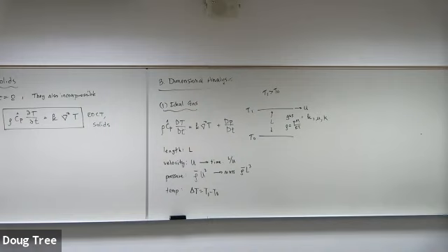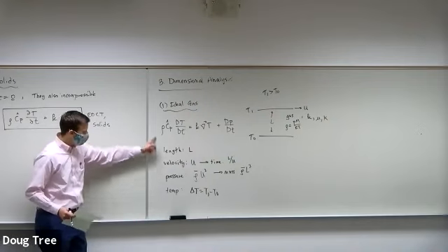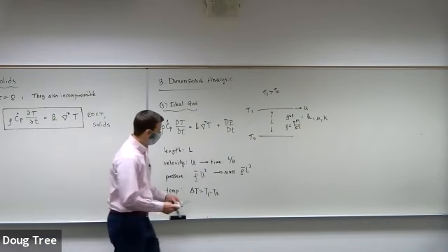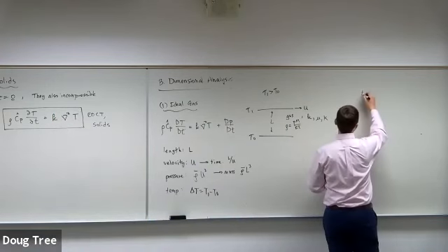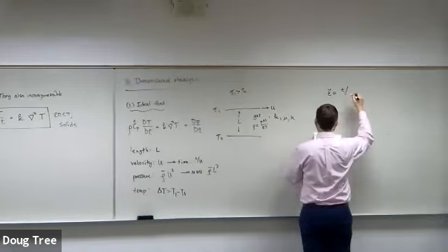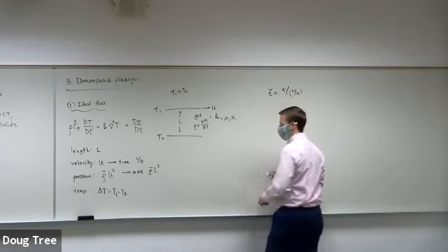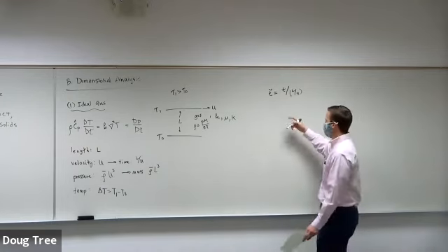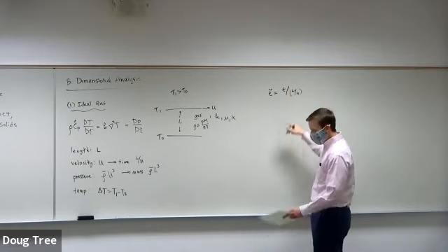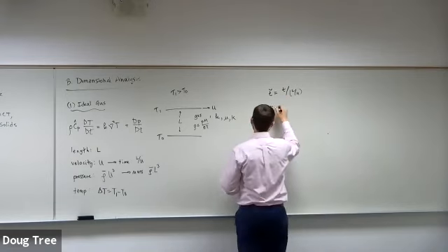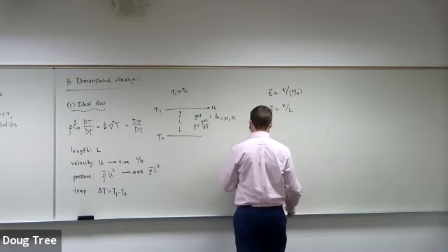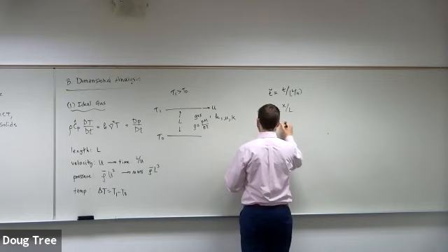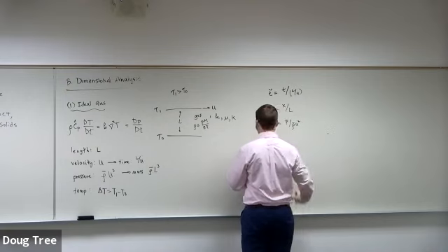Now we get to Andrew's step. Now we need to define all of our variables in the problem in terms of these dimensions, right? So for instance, I'm going to make a time, which is time divided by L over U. So for every one of the dimensions, where this has dimensions of time, I need to divide by the time dimension. If I have x's, I have x divided by L. If I have pressures, I'm going to have pressure divided by rho bar U squared.